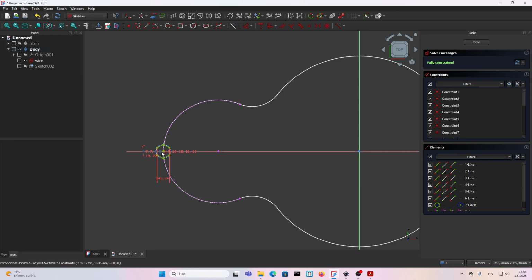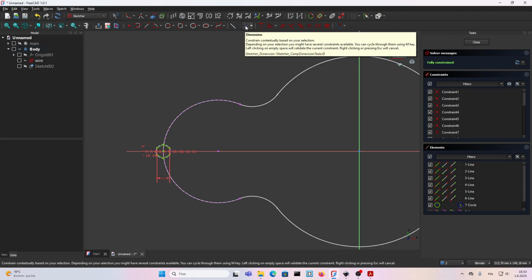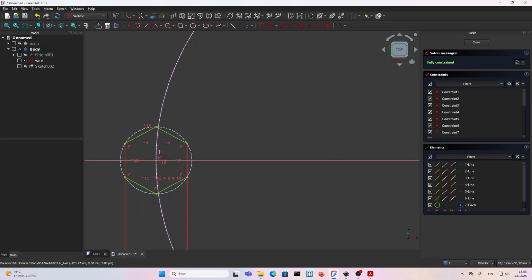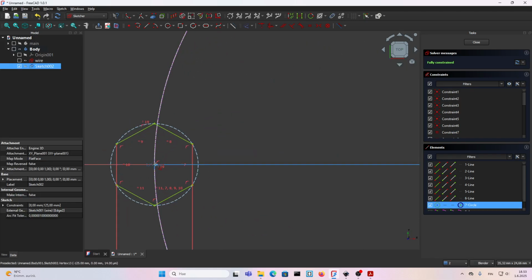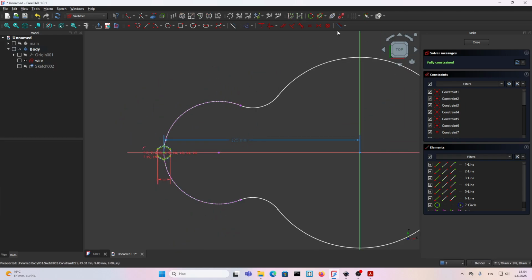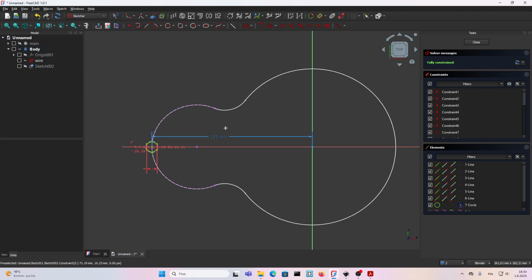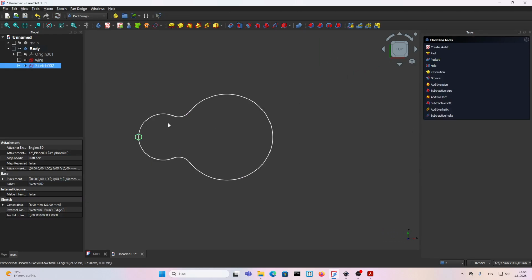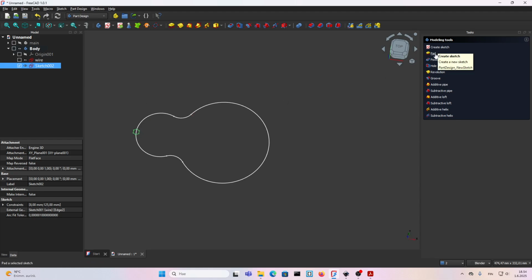This position, remember this one. The dimension from here to here is, I will click on here, reference constraint. Now we have this blue. Click on it, blue dimension. Click on this dot. Take a look. This dimension in here, I will turn this to red again. Now this dimension in here is 125. Remember this. Close it. Let's pad our sketch.